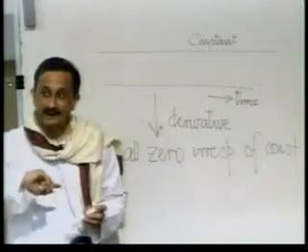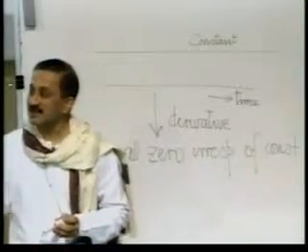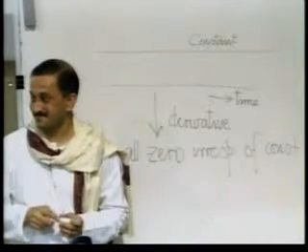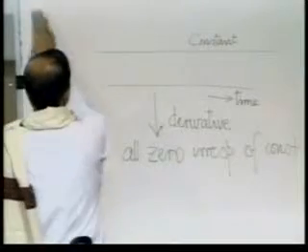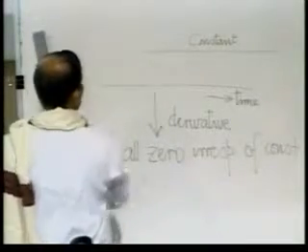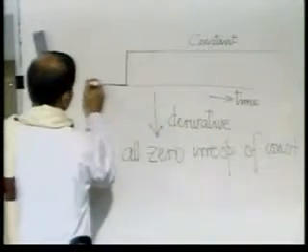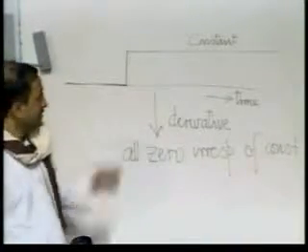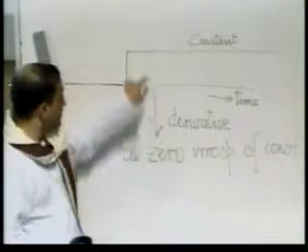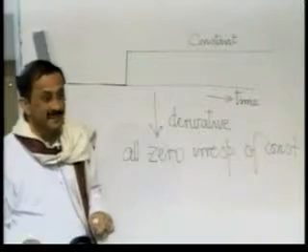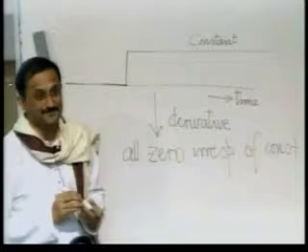When we try and apply a running integral on an all 0 function, it seems to lead to an all 0 function. But if you happen to have a function which is constant starting from some point onwards, then of course the doublet, when operated on this, would give you an impulse at this point, and then there would be no trouble, because if you took the running integral, you would get back the original constant correctly.